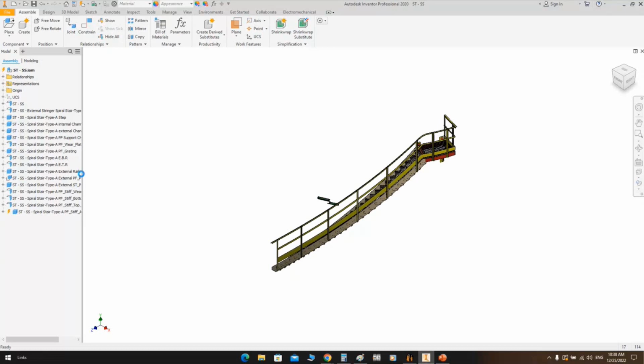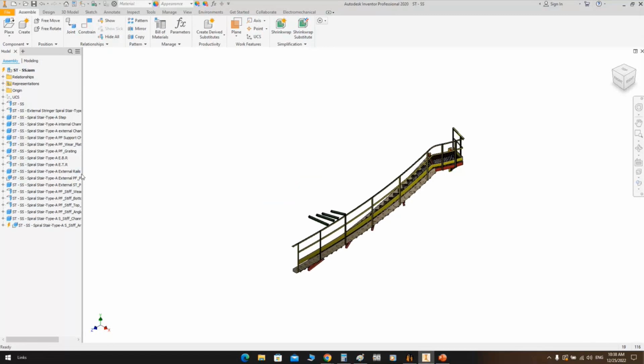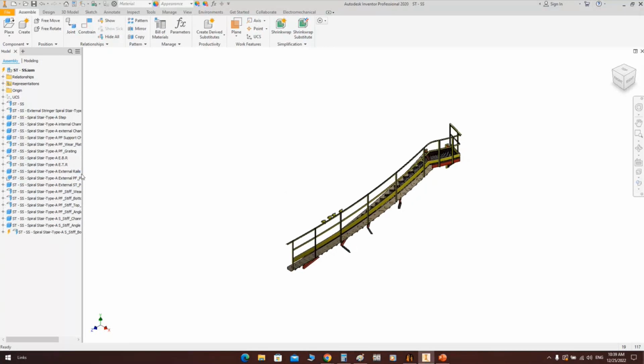From this point, I started creating some parametric models by making a link between an Excel sheet and Autodesk Inventor. That was in 2009. I started making a relationship between Autodesk Inventor and Excel sheets, preparing Excel sheets which give the dimensions automatically. For example, if you would like to change the size of a flange, just from the Excel sheet, select the size, and automatically the dimensions will be sent to Autodesk Inventor. That's the first step in parametric modeling.